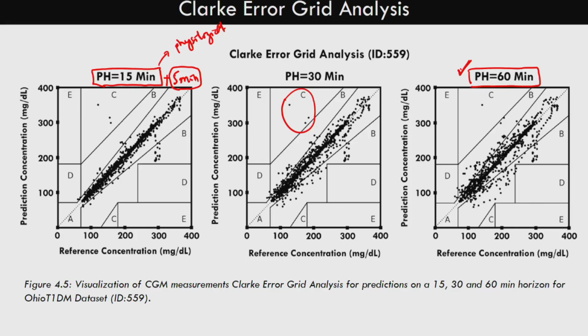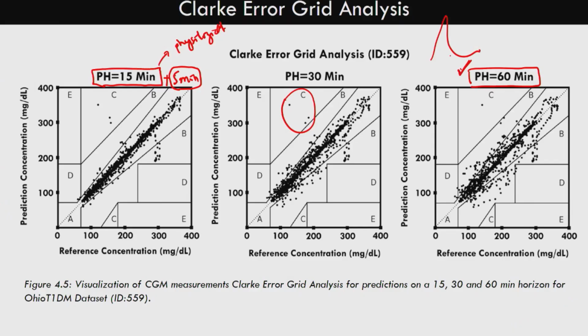Great. And you also mentioned different noise, drift and stuff like that. Are you also accounting for any movement artifacts? Movement artifacts are generally very fast changing. Let's say if I move my hand, it's like a very fast peak, so this you can remove using a low pass filter. Okay, so that filtering is already there, low pass filter.